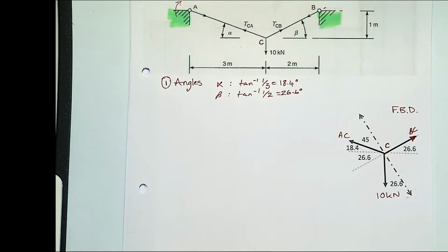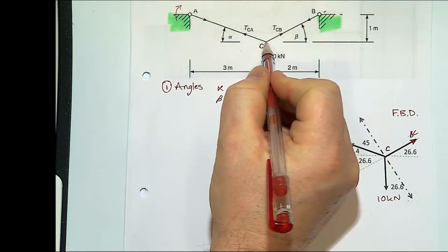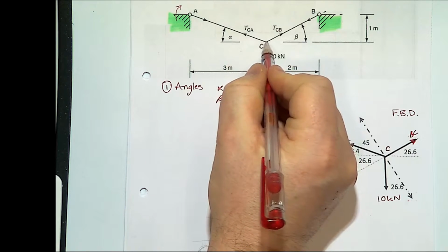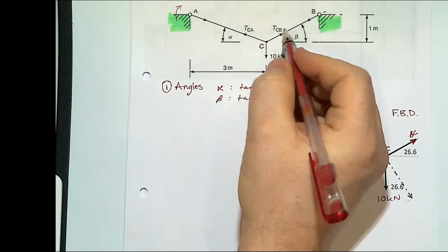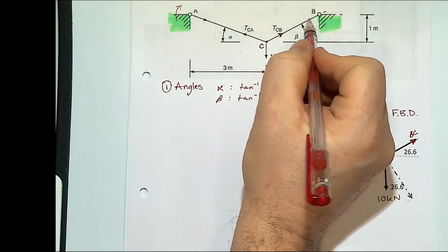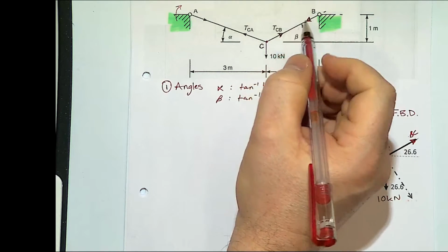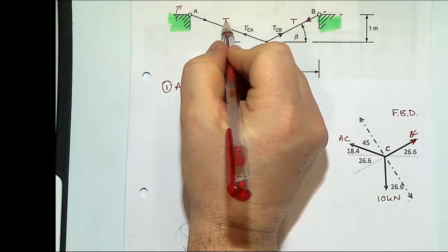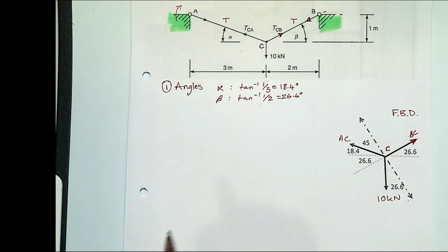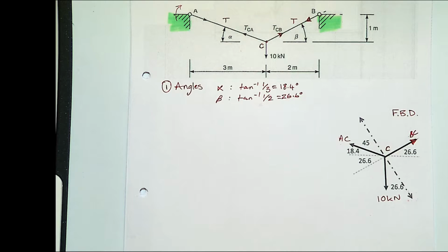So it's the same as when we were looking at trusses, that you've got a force pulling downwards, therefore there needs to be forces upwards to make sure that this point C doesn't move, that it's in equilibrium. If you've got an arrow pointing towards the middle of the cable, you'll have an arrow pointing inwards there, and both arrows pointing inwards is tension. So it's the resistance of the cable to the forces pulling it apart. So the arrow directions are easier within cables.